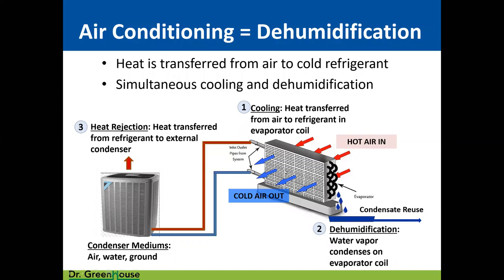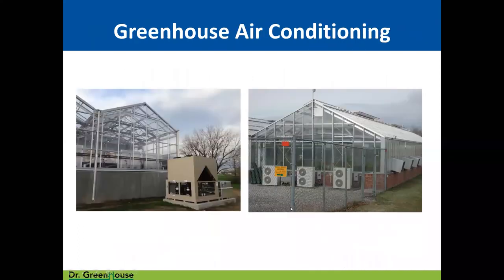before it gets delivered through the vents in your dashboard. And so with air conditioning by itself, we're creating these very cold coils with refrigerant or chilled water. As long as the surface of these coils is less than the dew point temperature, we are going to condense water out of the air. That's what air conditioning is basically doing. It's cooling and dehumidifying simultaneously.